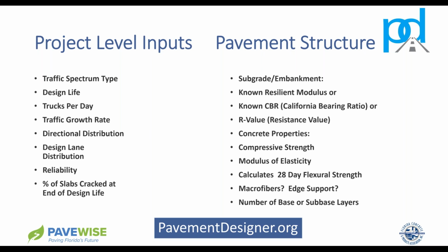Now, we don't use CBR here, do we? But a lot of states use the CBR. If you know what the CBR is, you can use it. Some of you folks here may know what the CBR values are of the soil. Or the R value, that's the resistance value that you get from a test that you do in the field. So that information you usually get from the geotech or your geotechnical report.